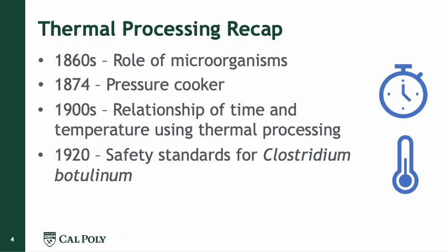We also can use a process that is called hot fill process that is used for the Gatorade beverage, and also for jams and jellies, which requires the temperature to be 85 degrees Celsius. Then we have sterilization processes at 121 degrees Celsius, and depending on the type of product, it can vary.